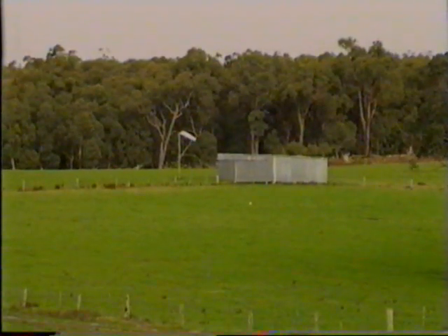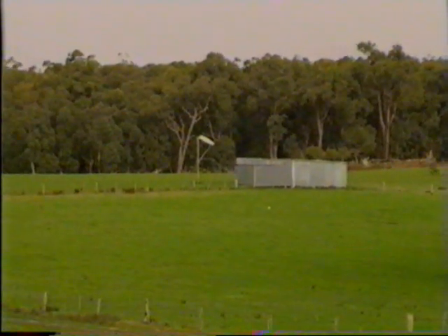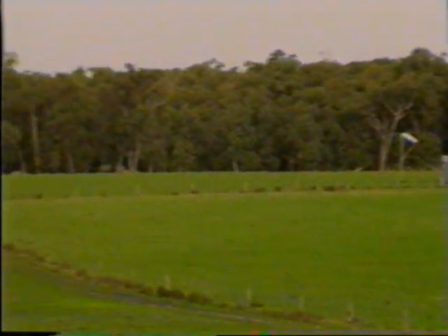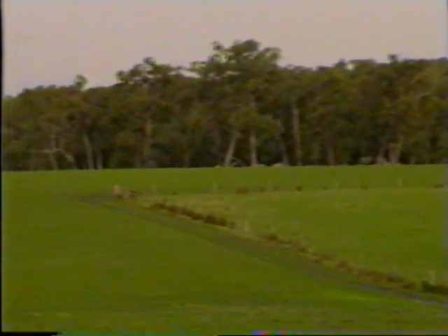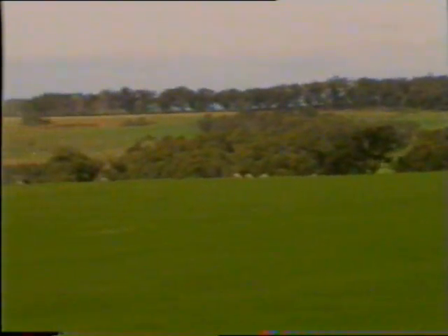Now, the other problem we do have here is if we look back up to the west, we have a blanket of trees down the side, and we have the wind coming over the trees. As we come out from behind the trees, as can be seen out here, the area is clear, we'd get a very strong crosswind effect, and we'd just have to be ready for that. We'd have a lot of turbulence, and the aircraft would want to weathercock that way. And it'd be about halfway down our takeoff run.